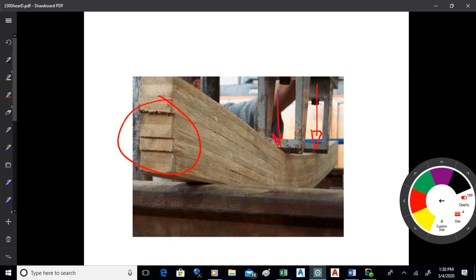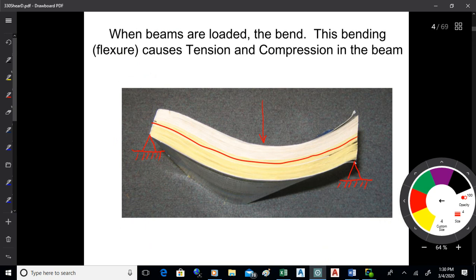It's like the pages of a book when you bend it. Here all the pages are sliding one across the other, whereas on the other side they're not, right? Because the book is bound. But the shear we're talking about is a sliding failure between those planes. The key word there is slide. This thing slides, that's shear, okay? That's what a shear action is.